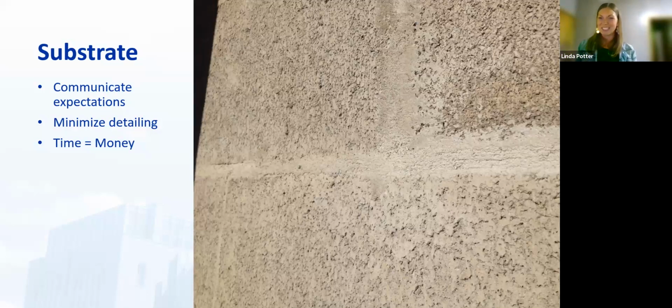And if you've ever seen a mortar joint, I should note to self, I'm going to put photos of what we don't want so you can see what I'm talking about. If they cut it flush, you still see all of these open pores. You still see a little bit where air is going to have a tendency to want to flow through those joints.